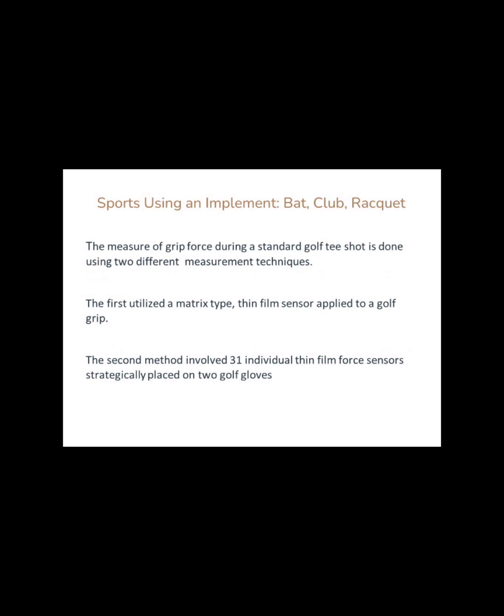The measure of the grip force during a standard golf tee shot is done using two different measurement techniques. The first utilized a matrix type thin film sensor applied to a golf grip. The second method involved individual thin film force sensors strategically placed on two golf gloves. In this case, the system is built using a pressure sensor by TechScan using piezoresistors.